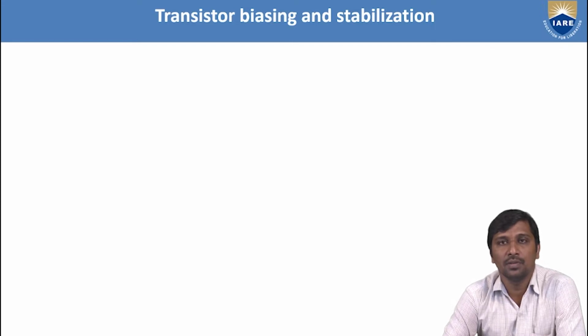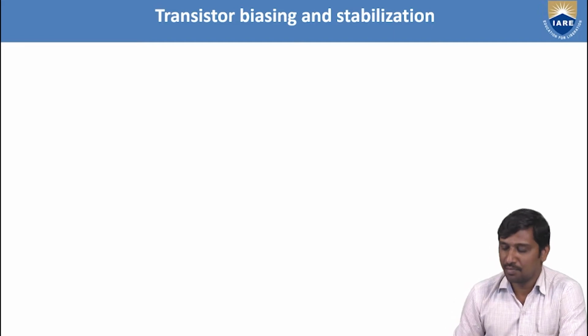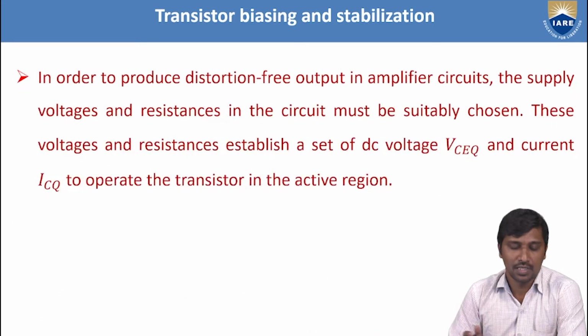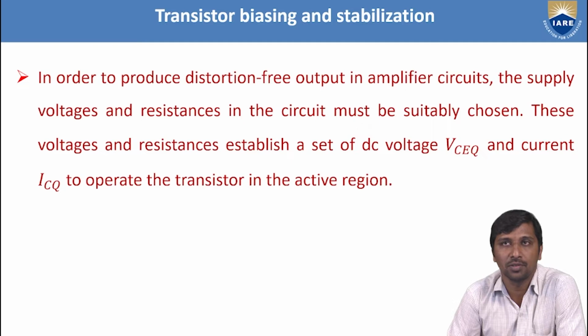If the transistor is to act as an amplifier, we need to make the biasing condition such that the input junction is forward biased and the output junction is reverse biased. We need to maintain proper DC biasing to produce faithful amplification, so for an amplifier circuit we require the biasing concepts, to produce a distortion-free output.